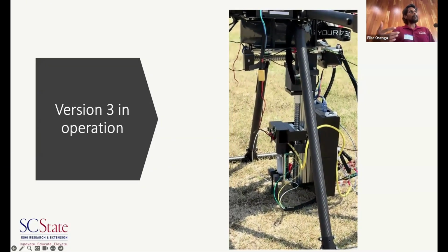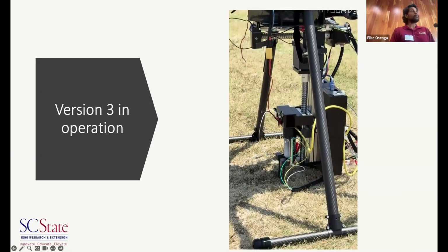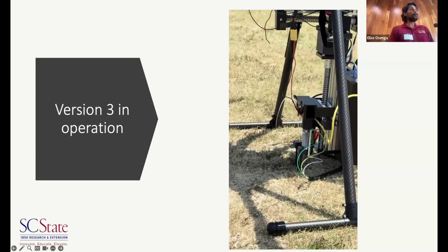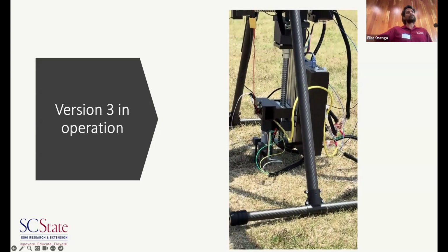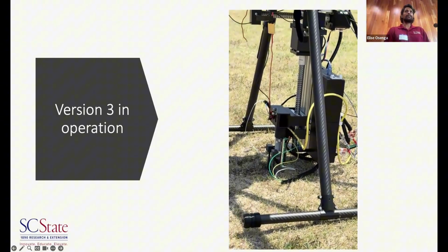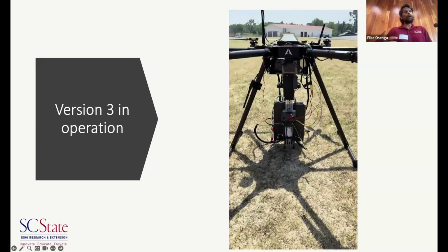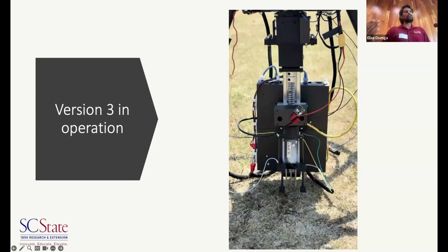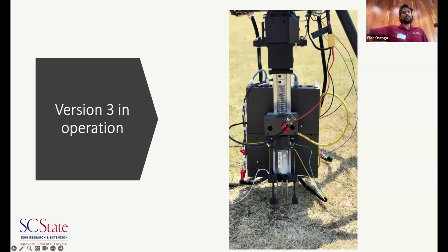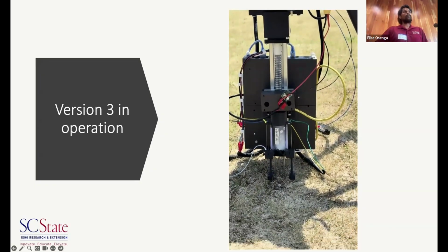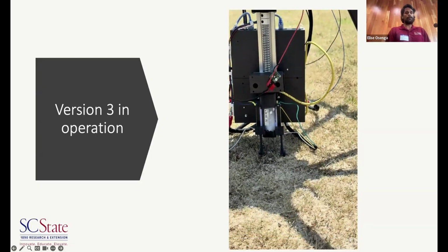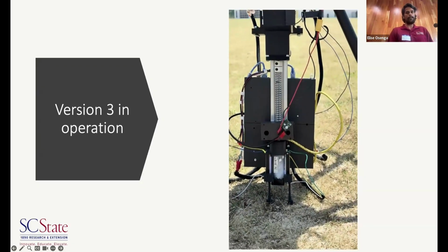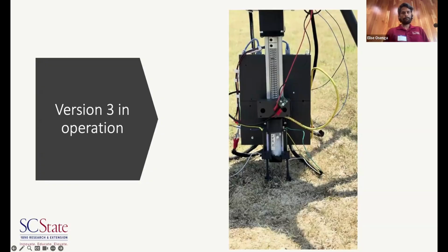So this is a fastened version to reduce the memory and also to not bore you guys, because at each location we do 3 insertions, and 3 insertions together take 10 minutes. It's kind of slow, I understand, but the reason to have it slow is the slower you insert the sensor into the soil, the better your chances of a full insertion. So that's why I keep it slow, and for safety purposes as well.